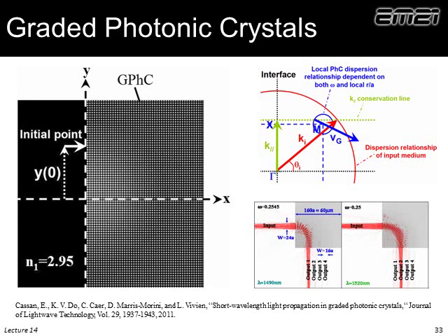Alternatively, we can operate in the photonic crystal region where we're chirping the size of holes, and we know as we get near the band edge, or the edge of a band, that it becomes very dispersive. We might even know this from circuit theory and when we design filters. When we get near the edge of the filter, the phase goes crazy. Well, here what's happening is we're chirping the size of the holes, and we're sort of surfing that band edge to tune refractive index by adjusting the hole size. And in fact, we can turn beams by doing that.